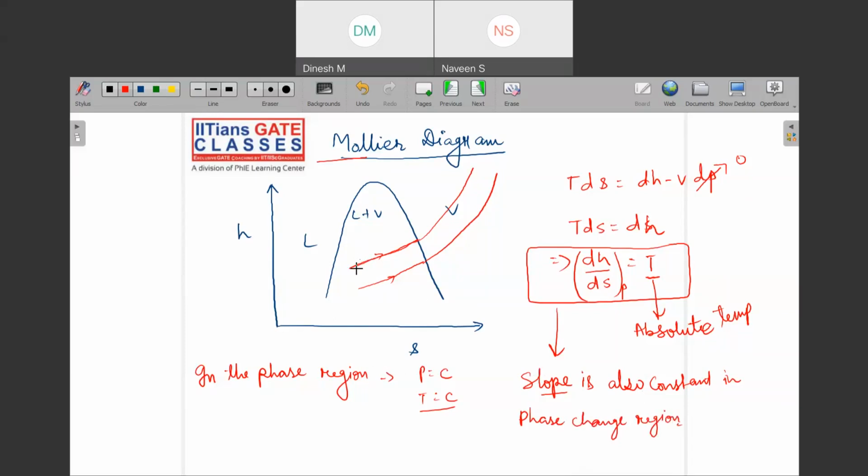What is more important to remember is that we are trying to draw constant pressure lines on the HS diagram, and constant pressure lines are straight lines in the phase change region, and curves with increasing slope outside it. Here your slope was constant.